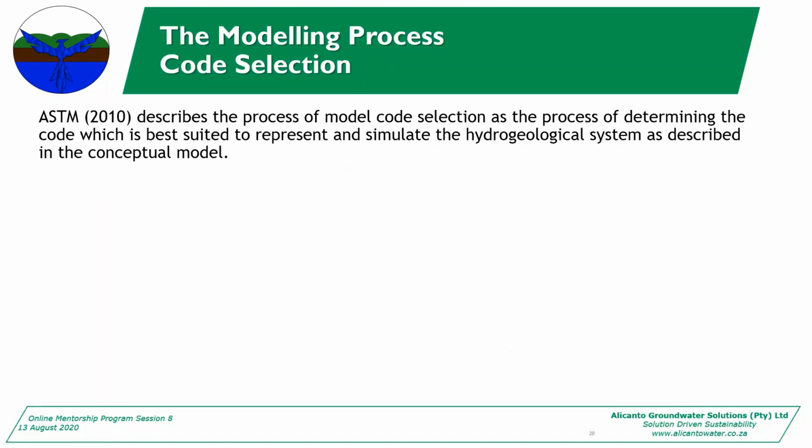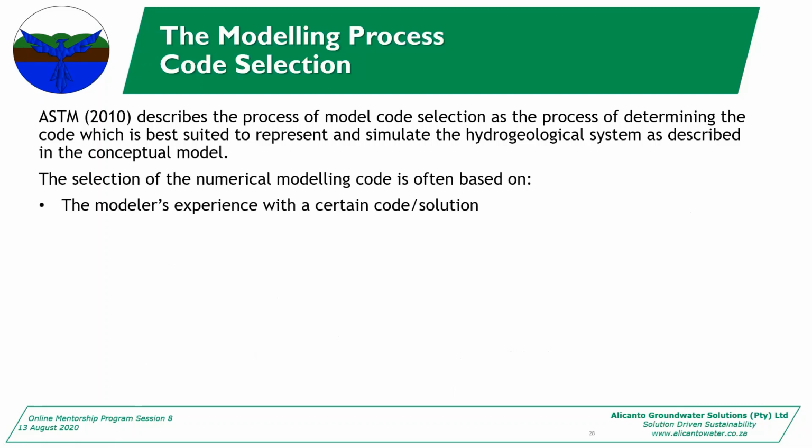The next step is your code selection. Yeah, when you're doing your code selection, you need to determine the code which is best suited to represent and simulate the hydrogeological system that you've described in your conceptual model, and also your model objectives.